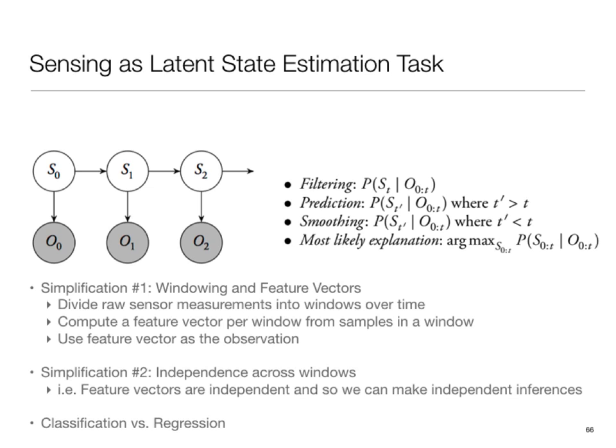So that's one simplification, right? You split the sensor signal into windows, assuming stationarity. What's the size of the window is something you'll have to empirically determine. And then for each window, taking those waveforms, you compute the statistical features that you believe are the important ones, and those are what are called features. So essentially, the segments of waveforms over that window, we reduce to a feature vector, which is basically nothing but statistical estimates computed over it.